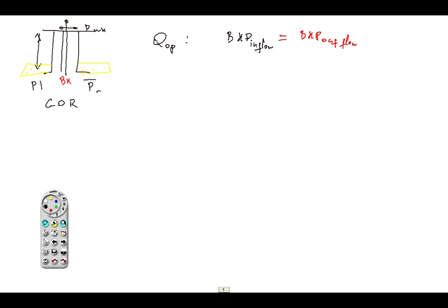When I calculate my inflow pressure, I start from the reservoir up. When I calculate my outflow pressure, I start from the surface down. So I need two equations describing my inflow and outflow curves, and then I need to find the rate at which this equality will be correct.